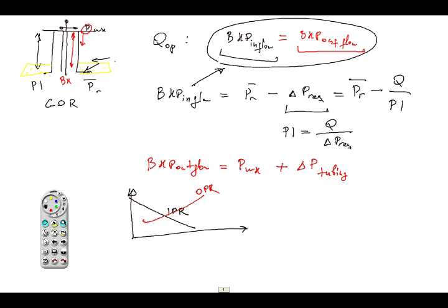By default we have well rate here starting from 0, right, and bottom hole pressure on the vertical axis starting from 0 up. So this intersection point here will automatically mean the solution of this equality, and it will give us the well operating rate and operating bottom hole pressure.